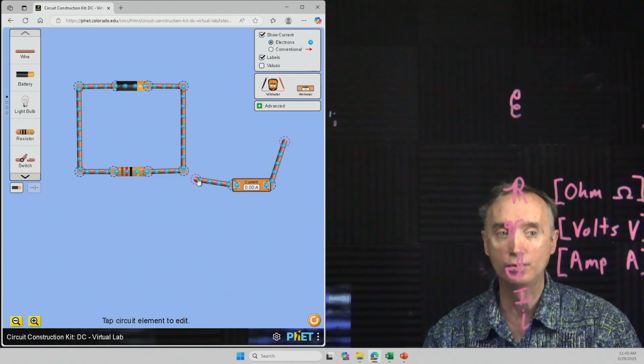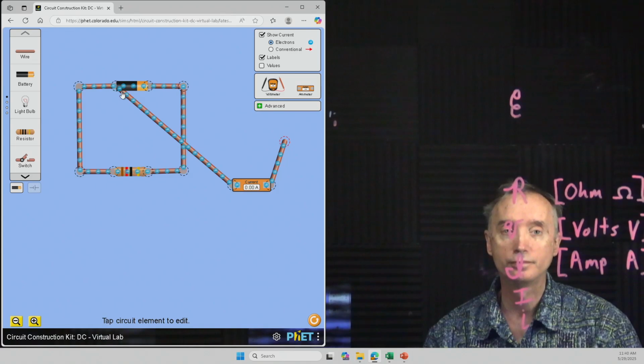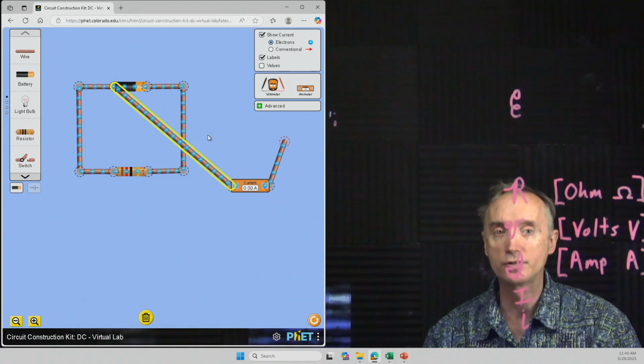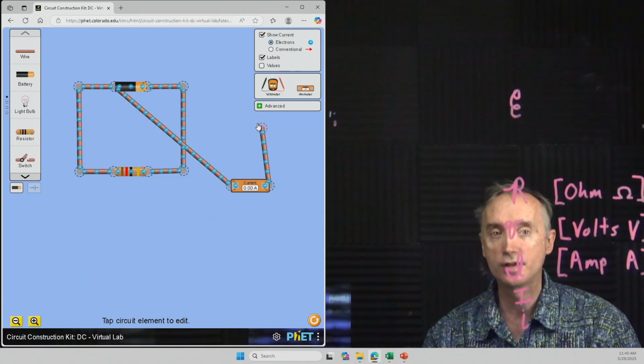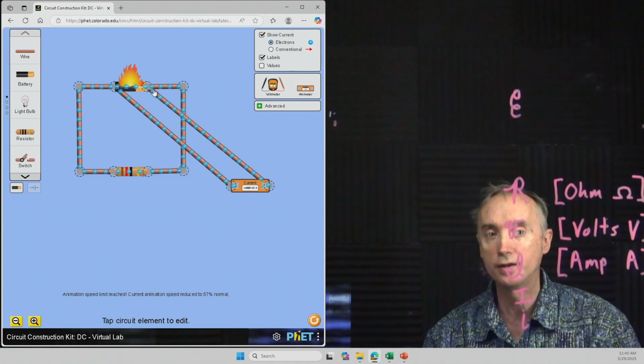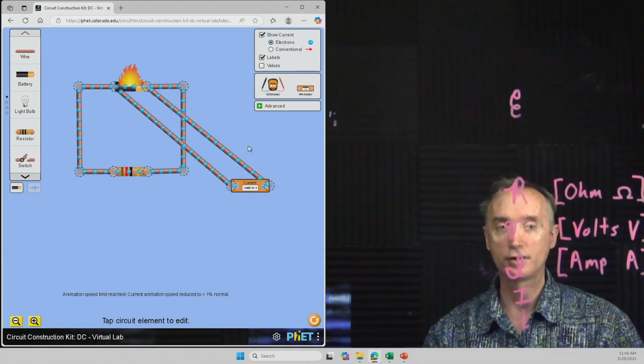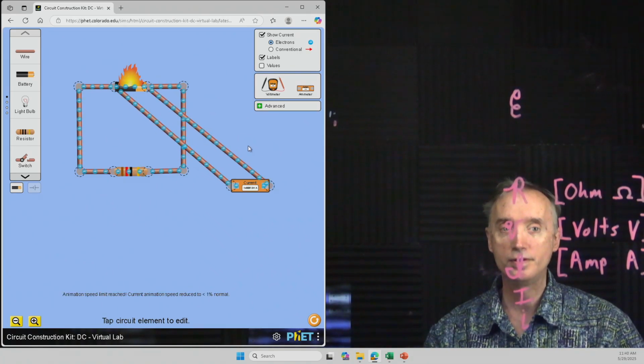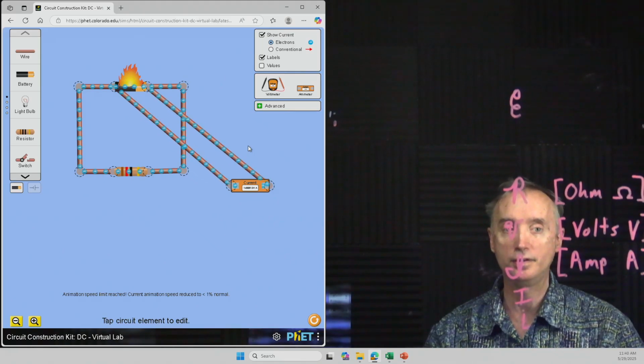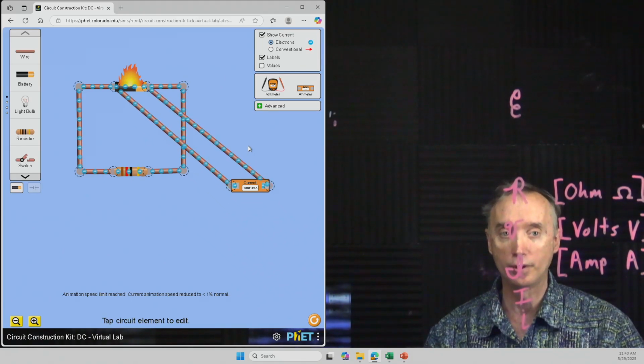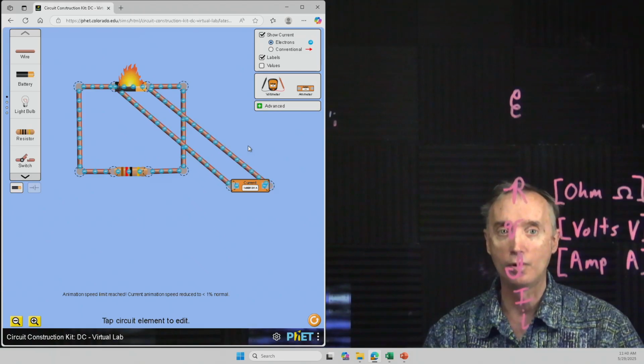Okay, so that would mean to do what? It means to take, here's our two probes, and we could take the two probes and we could put them over there. Okay, so I want to make sure that was connected. And then I'm going to take this one and put it over here, and uh-oh, it caught fire. So this would be sending too much electricity through the ammeter and it would blow it up. So you never want to measure a current this way.